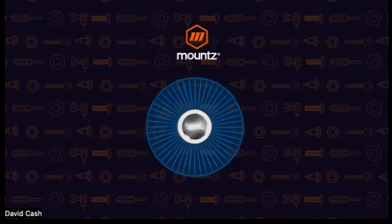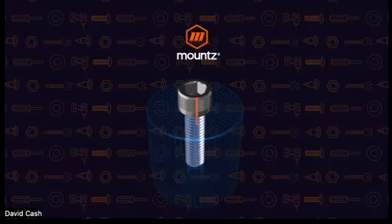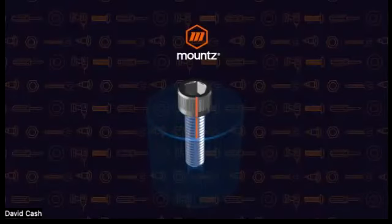And then finally, we have the marking test, where we put a mark on our part and we also mark the fastener. Then we will break the fastener away, realign the fastener to the line on the part, and measure what that particular torque value is. In the case of all those particular tests, if we develop a correlation or an uncertainty value between the assembly torque and the auditing torque, we can then say if we're getting X during our audit, we know that during the assembly process we are seeing what we'd want.